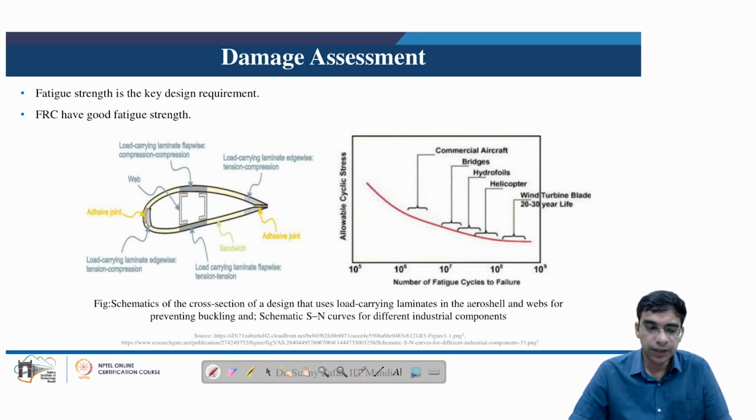So if we see the wind turbine blade in case of the performance analysis, the fatigue strength of the wind turbine blade is the key design requirement. As we have seen, the size of the wind turbine blades is increasing with every passing year. Therefore, the tendency of fatigue failure is also increasing.